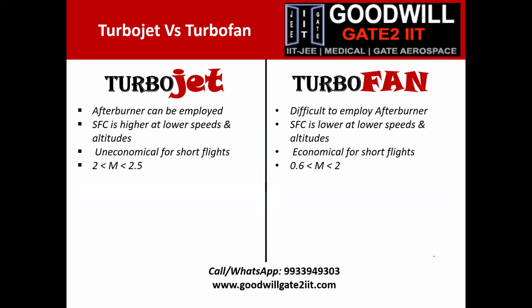Now, just to wrap up, when you talk about turbojet, because of its simple design, you can even use afterburners. Very easy to install. You can produce high thrust, run from enemies, do many maneuvers. Whenever you need high thrust, you can use them. Because turbofan is already a difficult engine, it is slightly more expensive, or it makes your design more complicated. So it is difficult to employ afterburners.